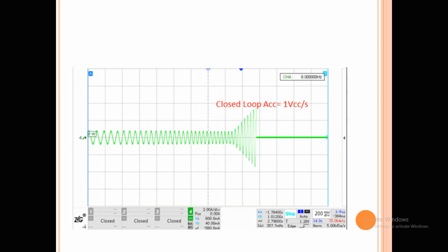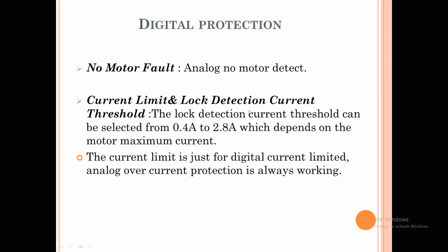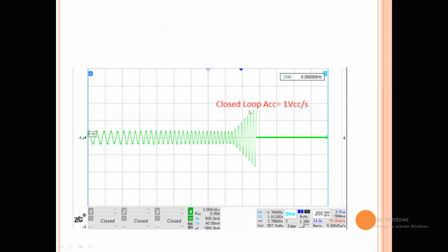This is an example of your startup failing. If you select a very high value, it might be possible that the startup of the motor operation fails, and it will trip and enable the overcurrent protection.